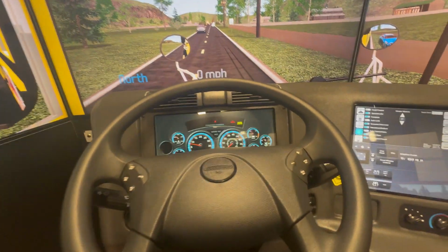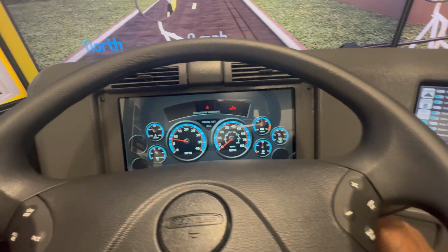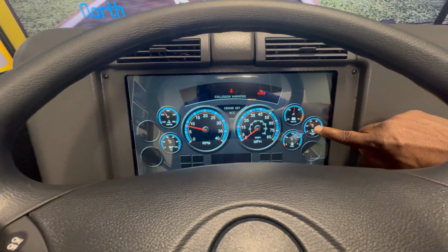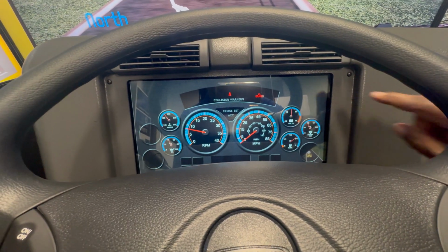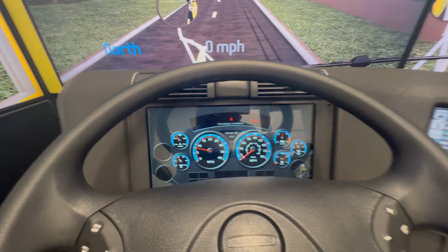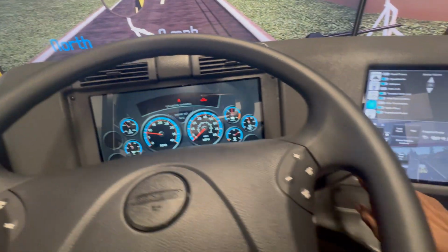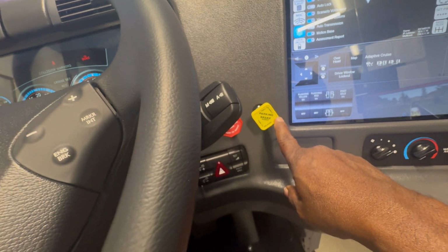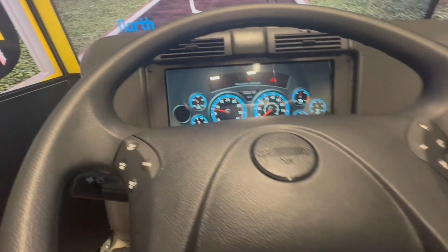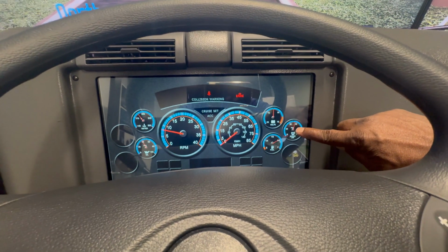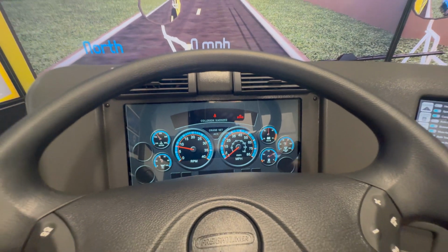Okay, so what you guys are hearing now is the low air pressure warning light and buzzer. It's on, letting you know not to move that bus or attempt to release the park brake valves, because the air pressure has to build up to between 120 and 140 psi.